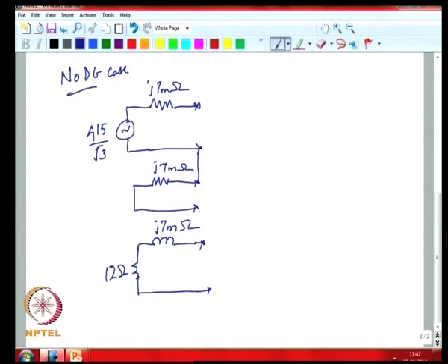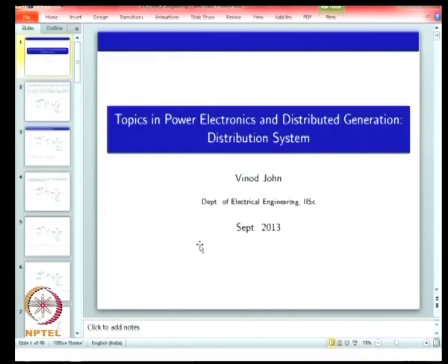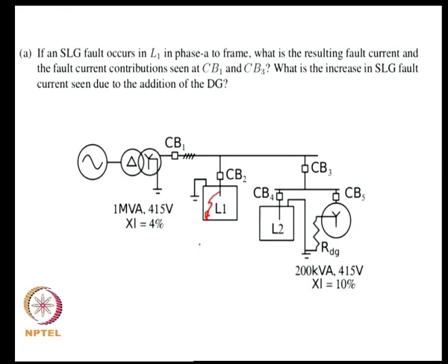and when you have a fault occurring within load 1, essentially the path for the fault current is through this electrode, through the system, out into load 1, into the frame of load 1, connected through the grounding wires into the ground electrode. That would also have a 4 ohm resistance, equivalent grounding resistance.